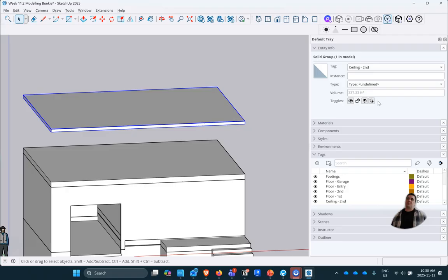One of the things you could also do with this, you could add 1/2 inch drywall as a ceiling on your lower level. So you can physically model that ceiling layer. And what that does is you could model your joists, or you could leave your joist cavity open. And so the ceiling, you could have that drywall layer that allows you to model this accurately. And then also when you cut it through section, you can kind of see that ceiling layer. But then you could actually leave your joist cavity open and model all your individual joists in there as well if you wanted to kind of go to that level of complexity.